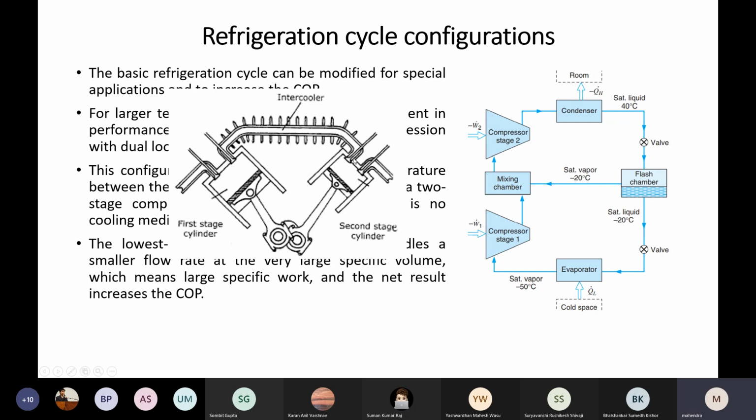Now, the same amount of air is passing over here, further compressing to 12 bar, but whatever temperature is raised is in an acceptable range. Then this air goes to the storage tank. That is the reason we have what we can call an intercooler. This is normal intercooling, or forced intercooling. But if the system is very big, an oil cooled intercooler is also used. Anyhow, this is the concept I want to explain to you.